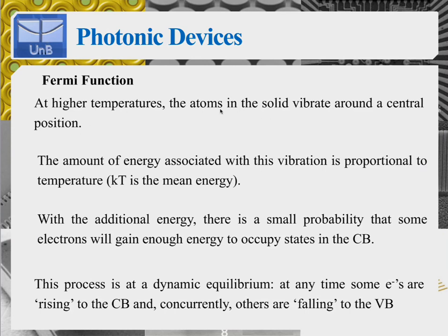Okay, this will translate in a solid being at a given temperature, and the amount of energy associated with this vibration is proportional to temperature. So it's actually proportional to kT, the Boltzmann constant times T, which is the mean thermal energy, the mean vibrational energy associated with temperature. And this energy, the energy of the atom's vibration, because we're at room temperature, will be supplied to some electrons which will be able to make the transition from the valence band into the conduction band.